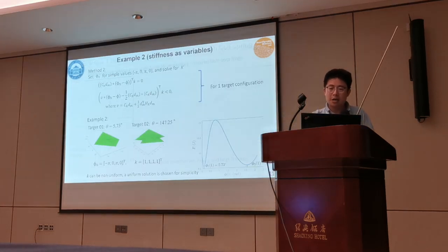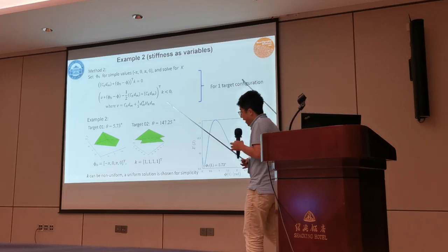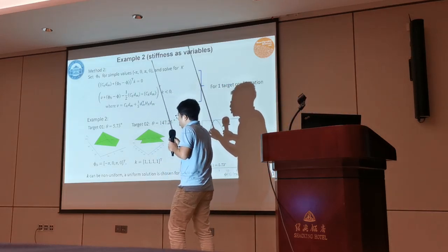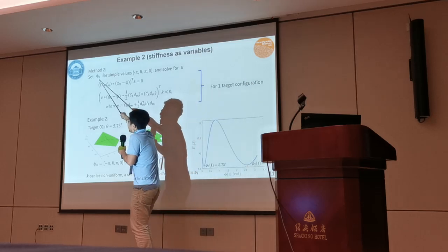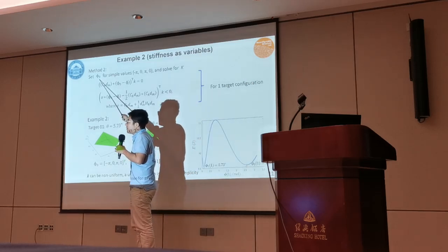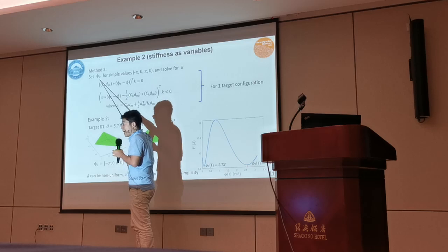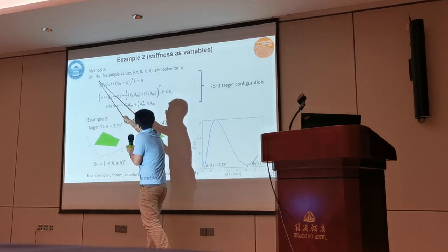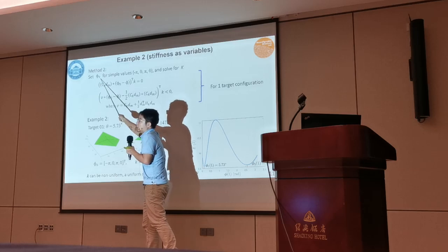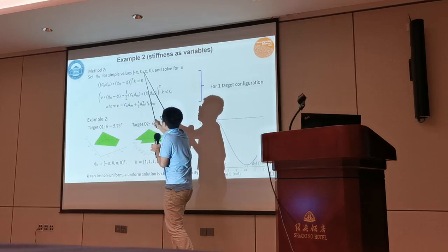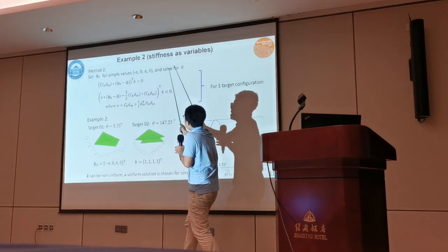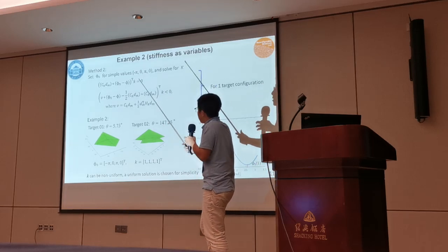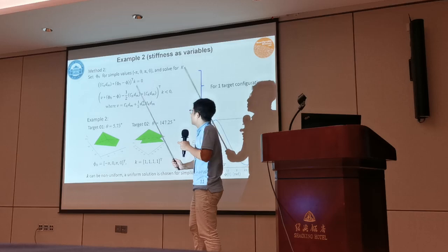So I made some improvement on simplifying the manufacturing, but how? Because this guy is hard: to manufacture a given rest angle is very hard. So I want to just use this. I can set some simple values for the rest angles, basically 0 or plus or minus pi, and then I solve for k. I chose a different set of variables because k actually is easy to design.